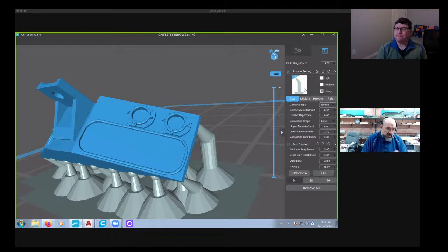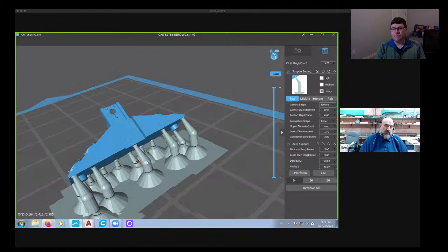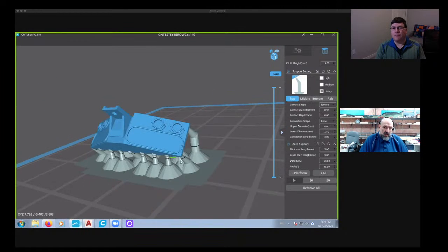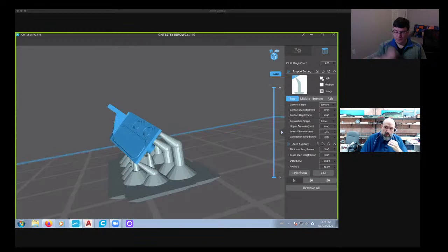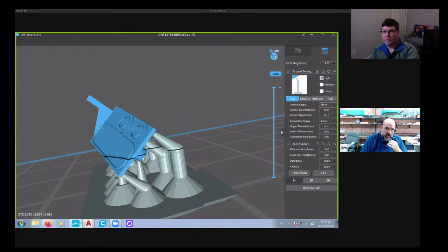If I was using an Elegoo black resin, we talked about the scale last week, about one side being super highly detailed but brittle, and the other side being very little detail but flexible, right? Well, the Elegoo black resin is way over towards the side of lots of detail and brittle. Right. So if you're using the Elegoo black, yeah, you can use the light supports. They'll print just great. Yeah. But because I'm using Siraya Fast Gray, which comes from that side closer to the middle, the light support doesn't print as well as the other one.